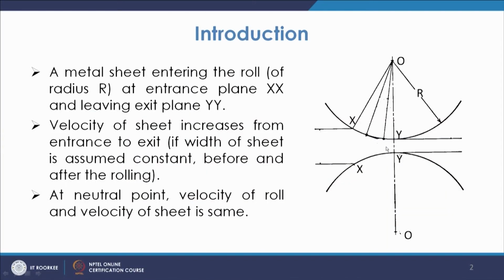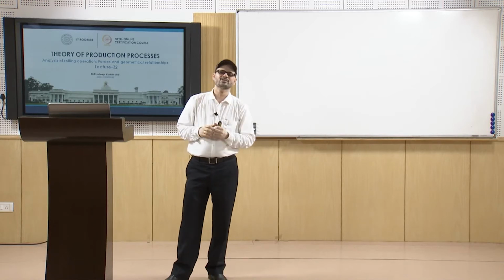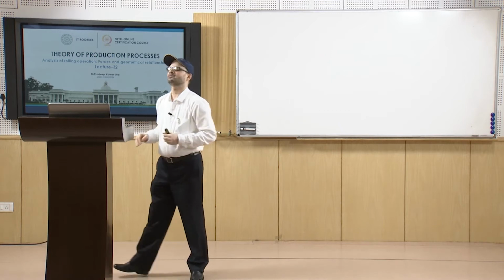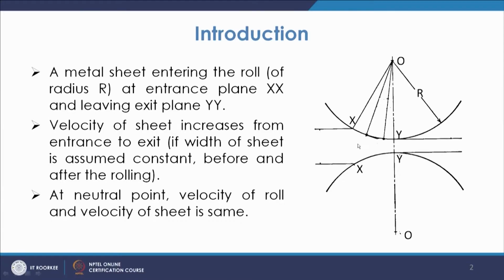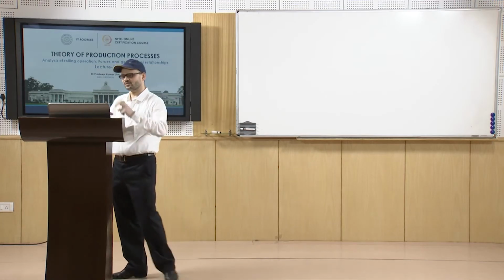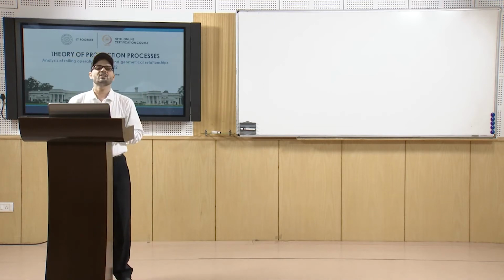When they are meeting, the friction force is generated, and it goes along the tangent direction. So once the rolls touch at this point, this force is generated. You have F here and P here in the radial direction. One is the radial direction and one is the tangential direction, and the radial direction is the force which is squeezing or compressing the material.